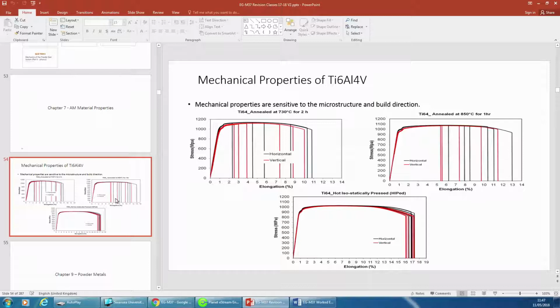So titanium 6-4 has a typical elongation value of around 17-18%. The as-built material coming out of the machine, what we found, can be as low as 1%. Very, very brittle. It depends a little bit on the quality of the powder and on the levels of oxygen in there. But certainly the level of heat treatment that's required shows that it's not just necessarily the composition having been affected, but those cooling rates have affected it somehow.